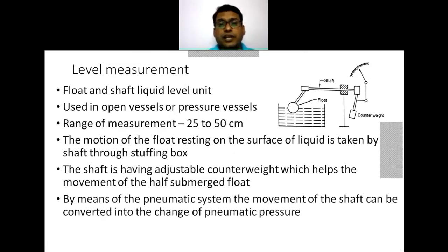Now, in case of level measurement, it is the float and shaft liquid level unit. This is generally seen in our household, where on overhead tanks we provide a float valve. The operation of the valve depends on the level: if the level of the liquid is increased or full, the float valve gets closed.